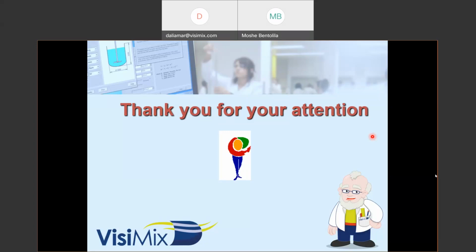Mixing effectively without baffles depends on the process. This is one of the points that I wanted to emphasize. For good mixing and a good process, we need to try to disconnect the mixing conditions from my process. For some processes, baffles will be very good. For other processes, baffles are a complete disaster. So we don't know. It depends on what your process requires. For instance, if you are breaking solids, you don't need the baffles, because the contact between the solid and your baffles may break your material, so we don't like to have it.